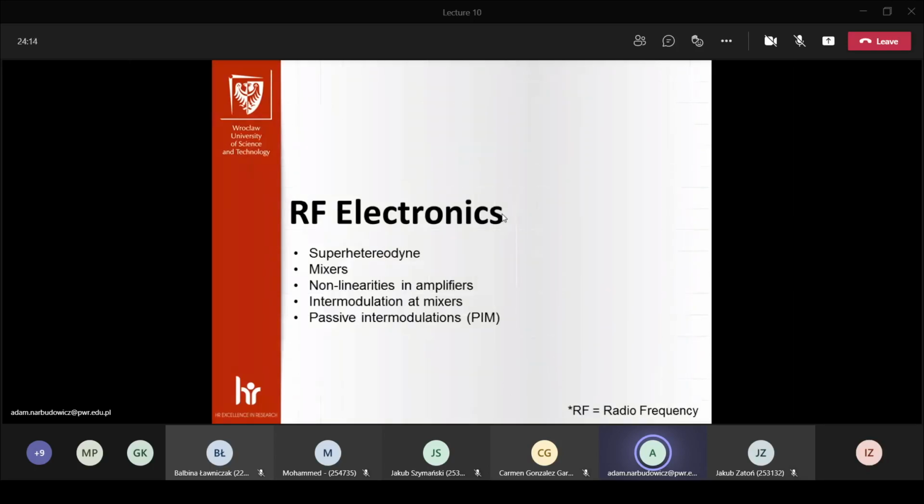And the reason for that is, as you saw previously, the art of modulation is very often changing the frequency of our signals. So what we're doing is basically creating new frequencies. So our output contains new frequency components of the spectrum, which did not exist in the input signal. And that's the core idea of how modulation works.